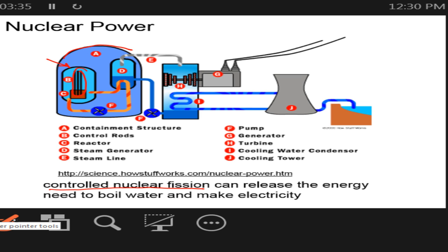Okay, fissioning of uranium-235, breaking apart that big heavy nucleus, releasing a lot of thermal energy. It's used in a steam generator to boil water, which comes outside of the containment, so a secondary loop passes through a steam turbine, connected to a generator to make electric current and sell it off to the grid. You then cool it. You either have a tall cooling tower, or you just put it into a lake. In Texas, we build power plants next to lakes to reject the heat.